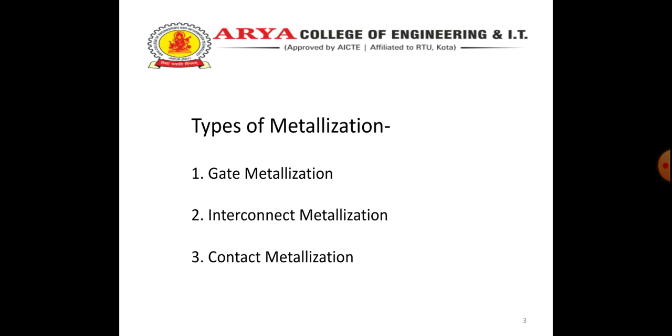Now, interconnect metallization. Interconnect metallization is one which interconnects thousands of MOSFETs or bipolar devices using fine-line metal patterns. Contact metallization. All metallization directly in contact with the semiconductor is called contact metallization.